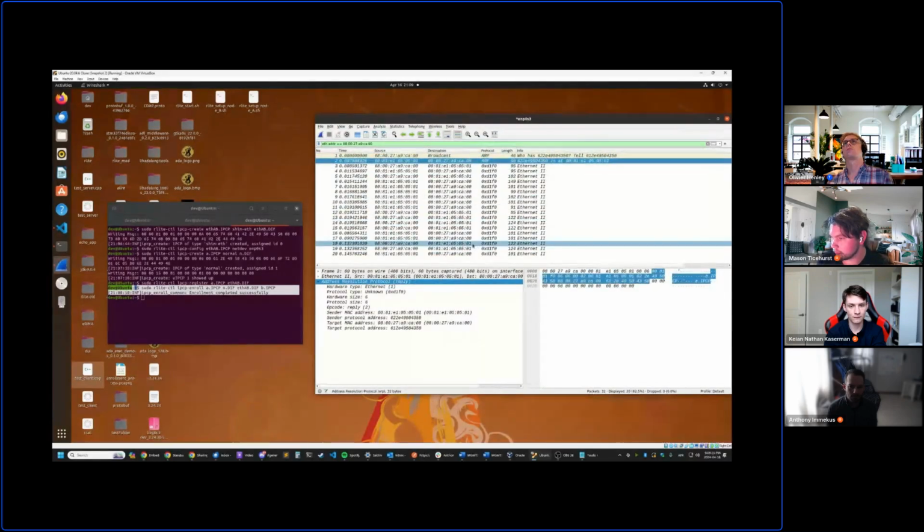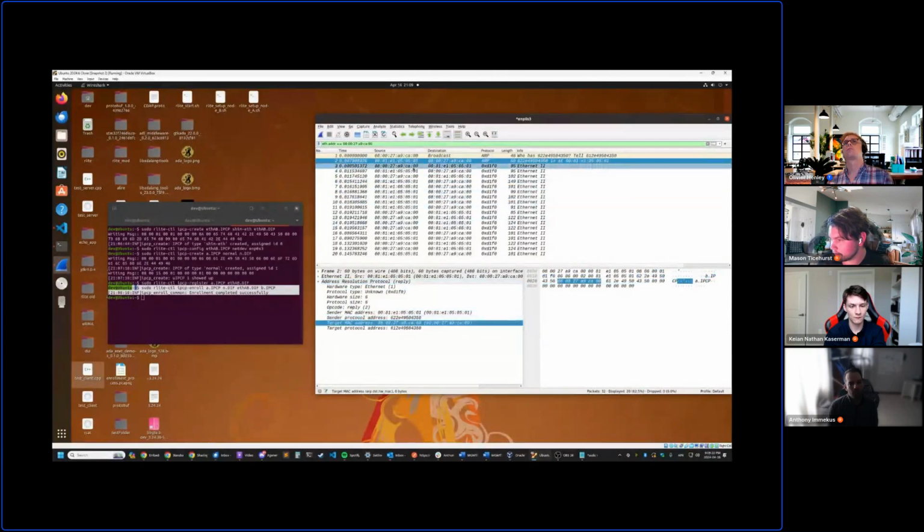Our embedded device saw this request. It internally checked, do we have an IPC process called b.ipcp? And it did. So it sent an ARP response telling the RLite side of things that we exist at this MAC address.